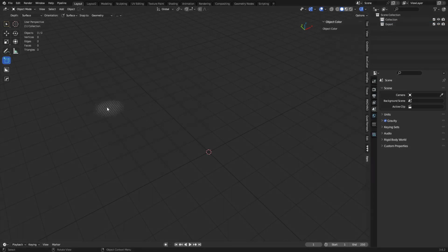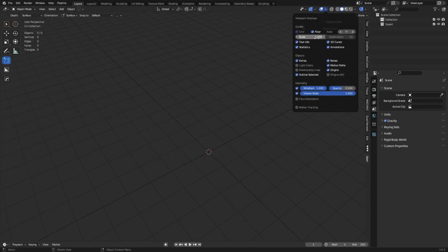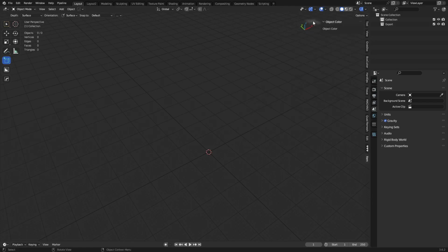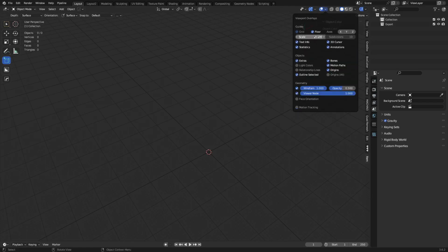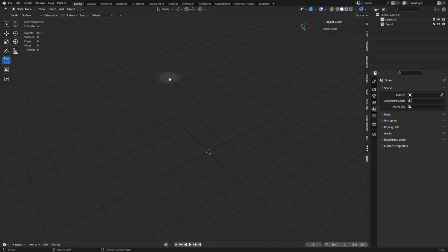Let's go ahead and delete everything, and we'll turn on geometry. Instead of using geometry snapping, we'll use default snapping. Okay, if we hold Control now, you'll see we snap every meter. These little squares represent meters. Matter of fact, if you want to change that, you can. So instead of using 1, if you want to do every half meter, you can do 0.5. If you want to do every 10 centimeters, you can do 0.1, things like that, right? We're going to use meter though, just for now. So set it back to 1, and you can see we're going to snap to meters.